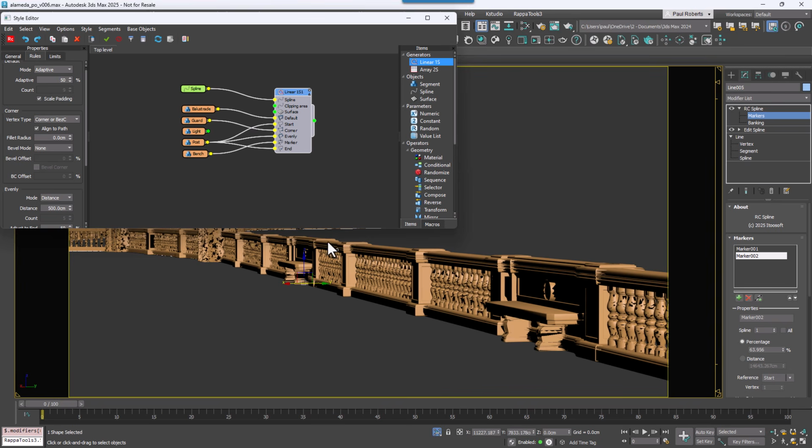And that wraps up the different inputs you can assign geometry to in a linear generator. But we're not quite done yet. There are two more node types to explore: operators and parameters. Operators are a central part of the RailClone workflow. You can use them to group items, create patterns, randomize geometry, adjust UVs, process splines, and much more.